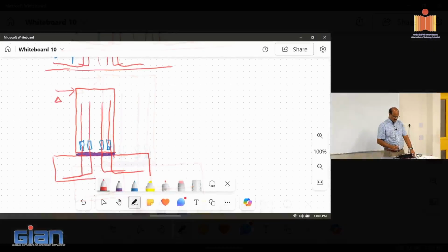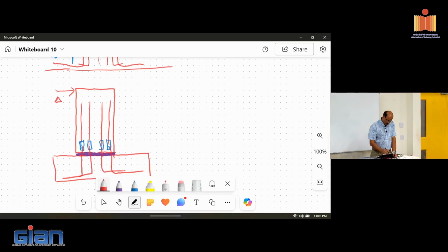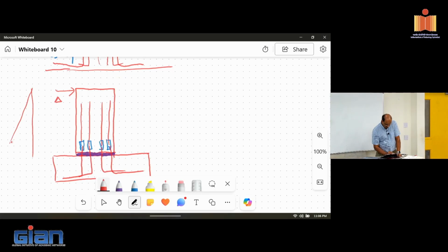If you look at the bending moment diagram for this one, it's the same as what you would expect. It's simple, your moment is going to continue to increase. But the strain profile will not be the same because this area gets affected. You have more steel in there. So whatever rebar is in this area is going to see much smaller strain.